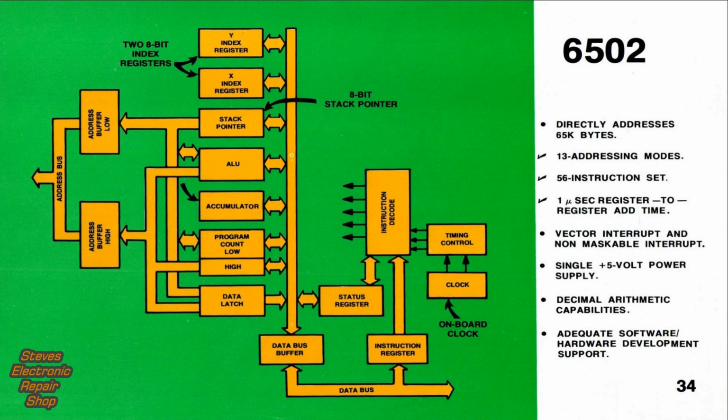Although the 6500 series is frequently thought of as an enhanced 6800, careful examination of the architecture disproves this. Notice that it has only 1 accumulator, and as shown at the top, the index register is broken into 2 8-bit registers. Also, the 6502 has a stack pointer that's only 8 bits wide.